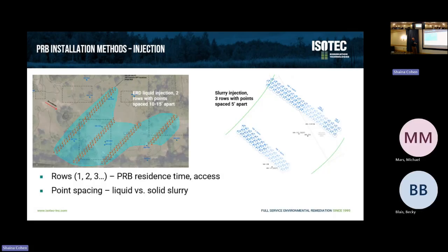And then when we think about hydraulic conductivity, seepage velocity, how much time in that barrier, or in this case, maybe if we have multiple barriers, both these cases, maybe if the groundwater is flowing in here, it may take traveling through 2 barriers to meet your remedial goals.